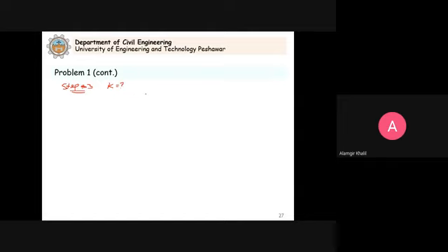So here we identify that, for example, if I consider rho Vd, it cannot be combined to form a dimensionless group. You take the product, you take the numerator, denominator, divide by anything. We cannot make a dimensionless group from these three. This is just an example. So it means that this K will be equal to 3. I am saying in other words that this K is equal to M.